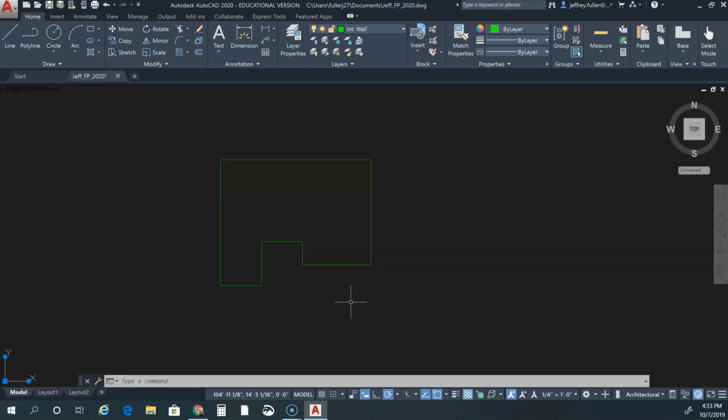So if you're going to use any kind of masonry siding or masonry finish on the outside of your house, like a brick wall, a stone wall, or anything like that, just go ahead and make the thickness of your exterior walls 10 inches. If you're going to use any other type of siding, make the exterior walls 8 inches. Okay. Now, that's really it for the exterior walls. The interior walls, we're going to use a common 4 inches on the interior walls. But right now, we're just doing the exterior walls. So depending on which one you're going to choose, either 8 inches or 10 inches, you're going to select all of your wall segments.